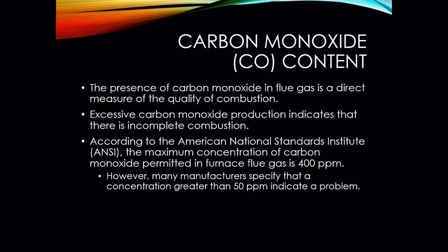The lower, the better. Like it says, according to the standard, we can have a maximum concentration of 400 parts per million, but in reality, I think that's a little bit high. We want to try to keep it down. Try to stay at 150 parts per million, and you're good. If you are having issues with carbon monoxide, you need to start inspecting that heat exchanger and seeing what's causing it.